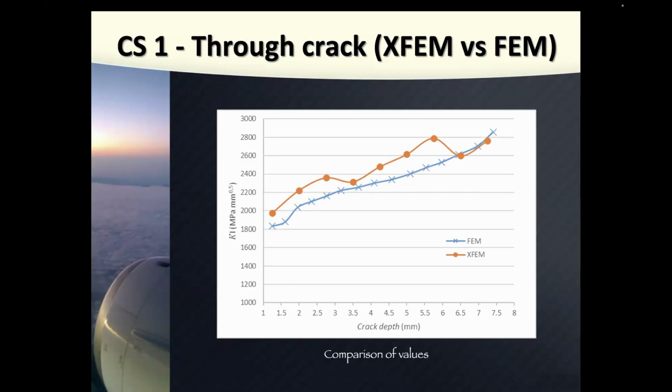If you ask me which of these two is better, ANSYS. Again, I explained why: because ANSYS creates a new mesh with every step. It does this automatically, which is a good thing. Here, definitely you have to play with the mesh. In ANSYS, you can literally start with a very bad mesh, but you improve the mesh only around the crack front.